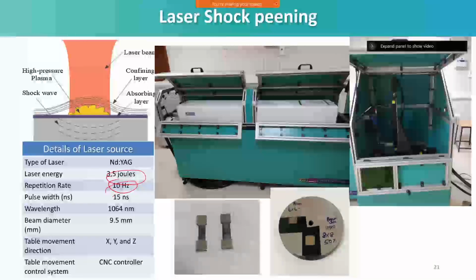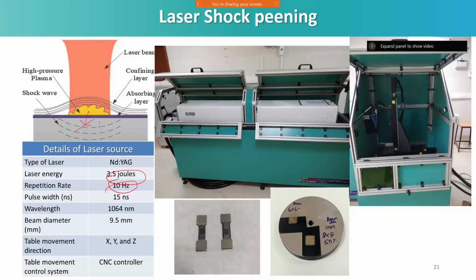Basically shock peening can be realized by constricting the evaporation of the laser exposed material using a water column, that leads to putting compressive residual stresses inside the material. That would be helpful in improving the fatigue property under cyclic loading. And for many of the turbine industries, we do this kind of shock peening over the surface of the material, which really helps in improving the fatigue resistance.